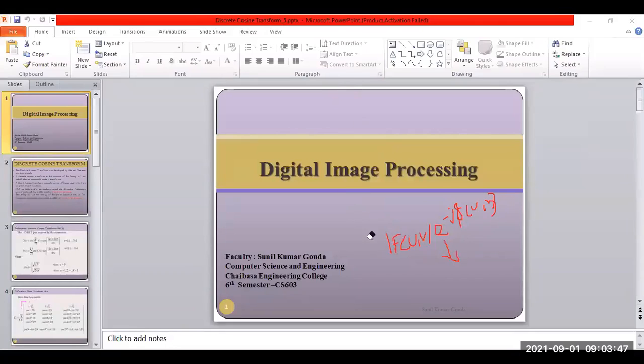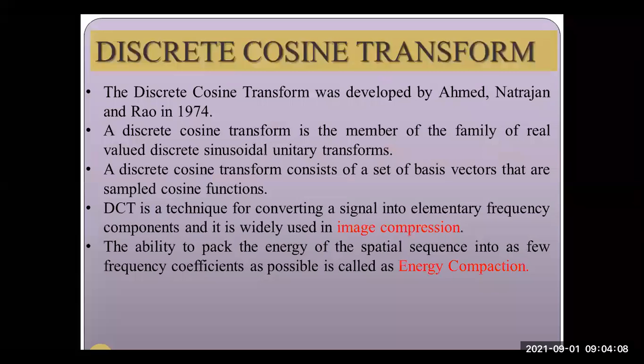So what is the drawback here? The drawback is that computation in the complex format is much harder. If you do any pre-processing or computation, it is difficult. So that is the reason we have gone for other transformations. One of them is the discrete cosine transformation, where the actual frequency domains are represented in real format, or we can say real cosine basis functions.